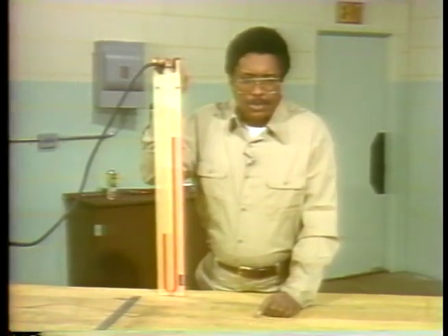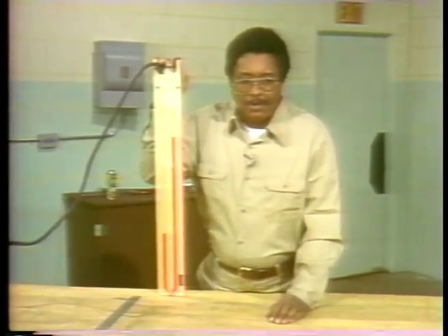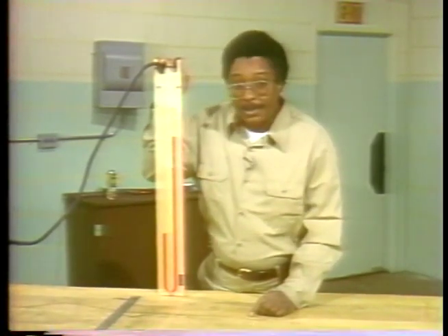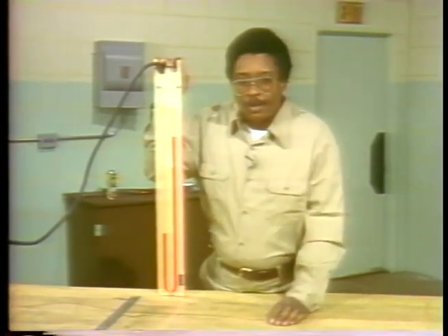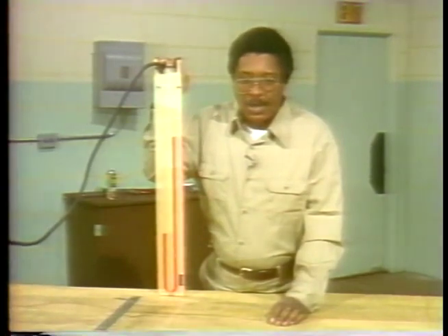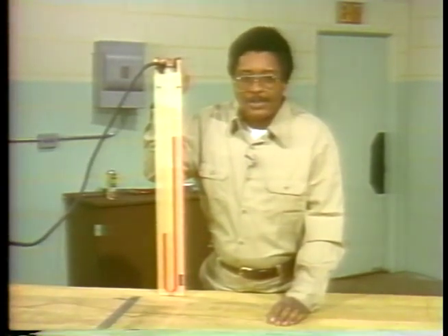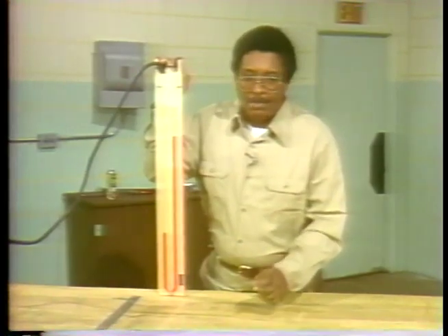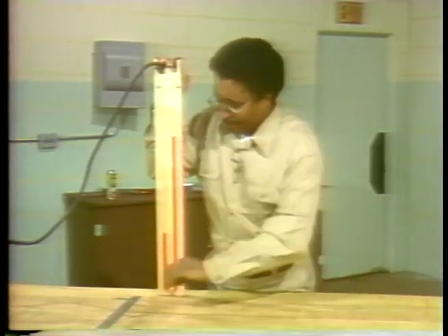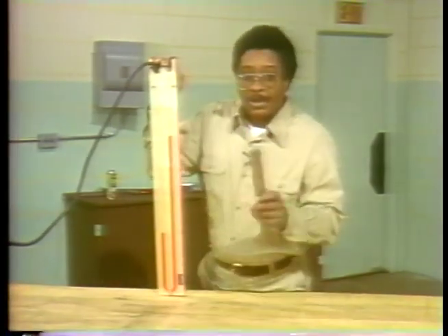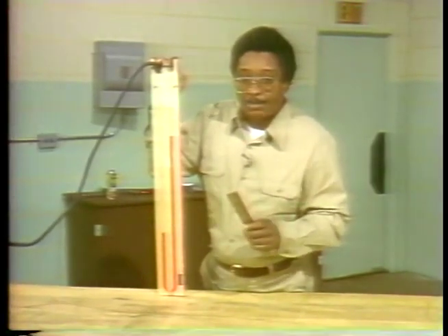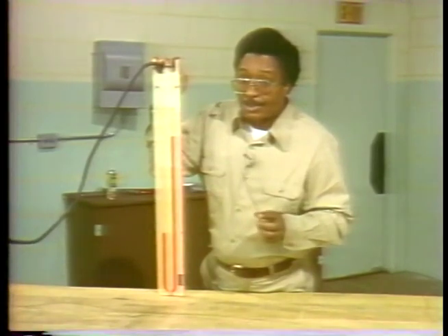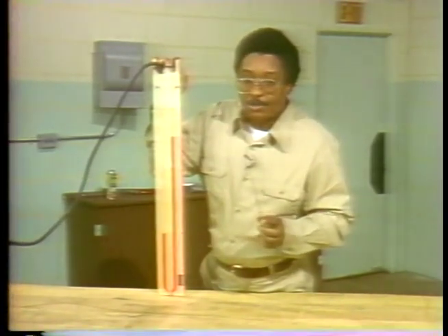We know that the pressure we're measuring is greater than atmospheric because the water moved away from the end connected to the source. However, in order to determine how much greater the pressure is, we must first determine the difference in the heights of both ends of the water column. We can do this by measuring this difference with a ruler. This distance is the height of the column which is being held up by the pressure. Then, with a simple calculation, we can determine what the pressure is.